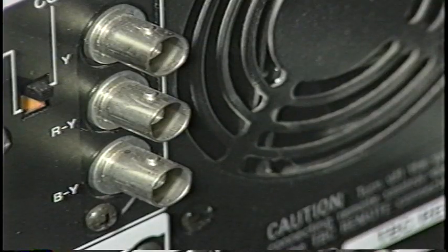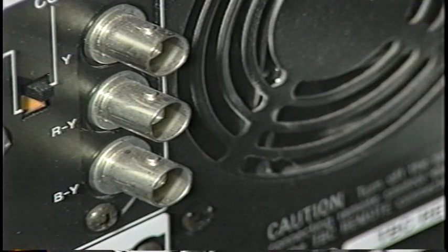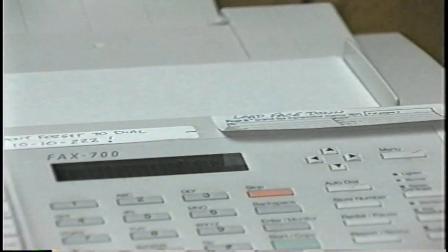If errors are observed on the test set, then something is intermittent or improperly assembled, and the cause must be located. By testing cable assemblies in this manner, potential future problems are isolated while the cable installer is still on site, allowing the problem to be fixed before the cables are turned over to the customer. A good rule of thumb with this test is, if in doubt about the integrity of a connector, replace it. It's better to replace a faulty component worth a few dollars than to risk the loss of service worth hundreds